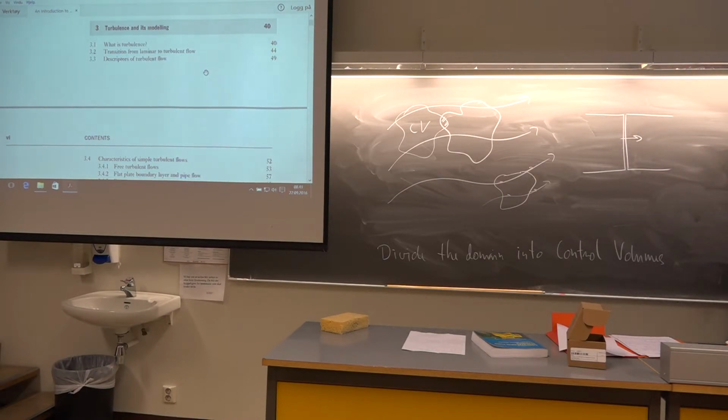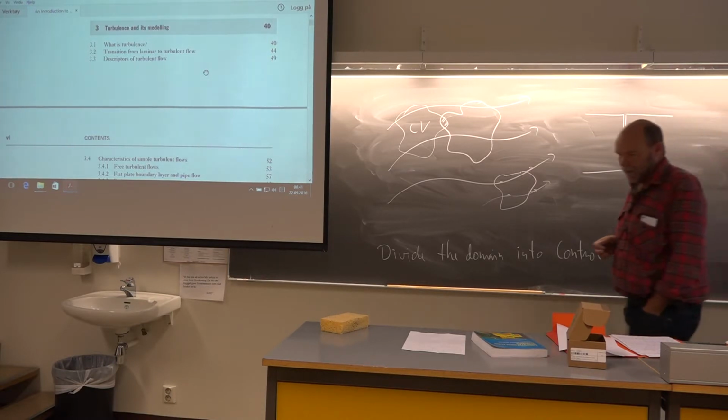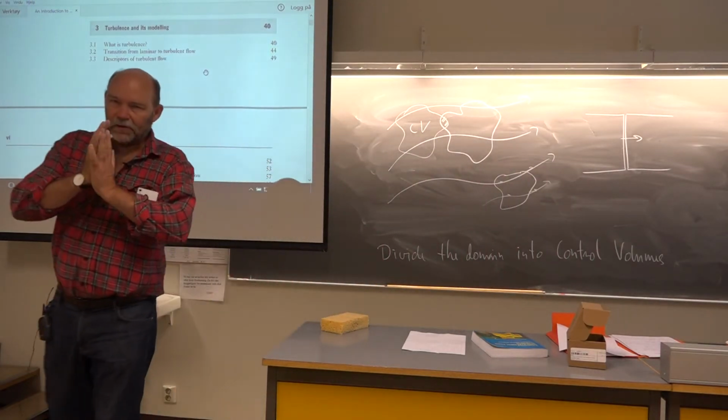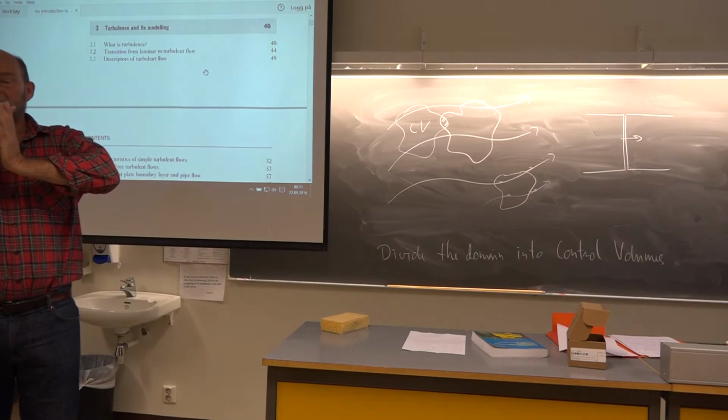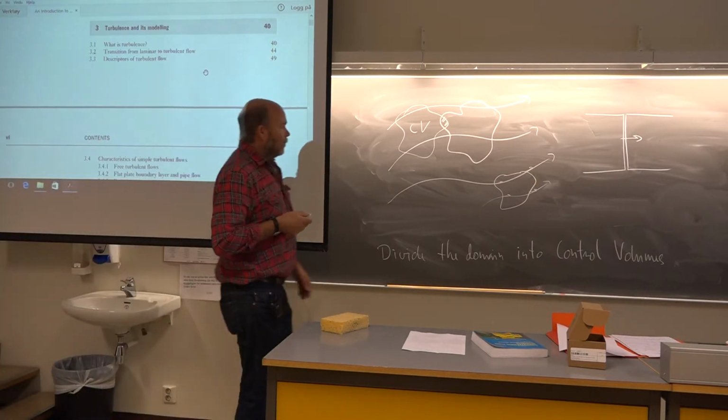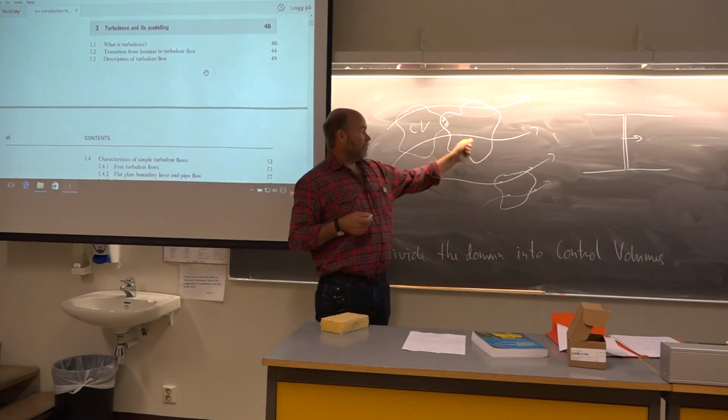Then you have better control of the transport properties. When fluid moves from one cell to the next, or momentum moves from one to the next, it is much easier to control it and get it correct. So typically what you're trying to do is to let the cells be face to face. But you don't have to. This would still be possible.